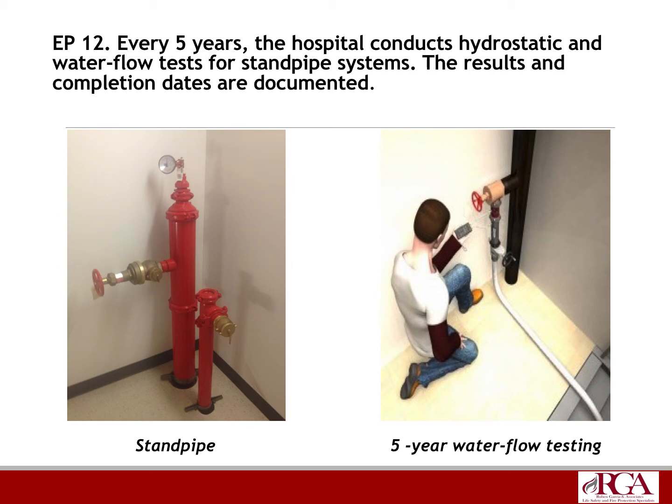So essentially, these standpipes that you see in the stairwells when you walk through the building are basically fire hydrants. They're there for the firefighters to hook up to in case they need to put out a fire that probably hasn't been put out fully by the sprinkler system. Because believe it or not, fire sprinkler systems are called fire suppression devices. They're actually not designed to put fires out, although 99% of the time they are actually going to put the fire out. They're going to douse the fire.